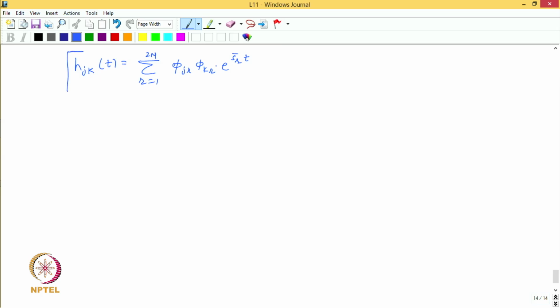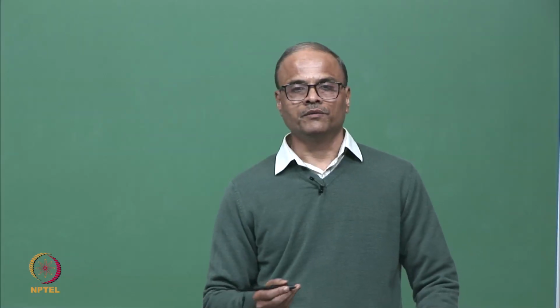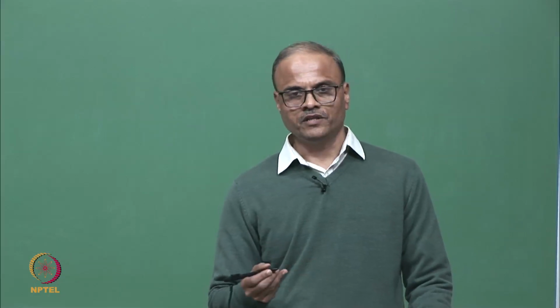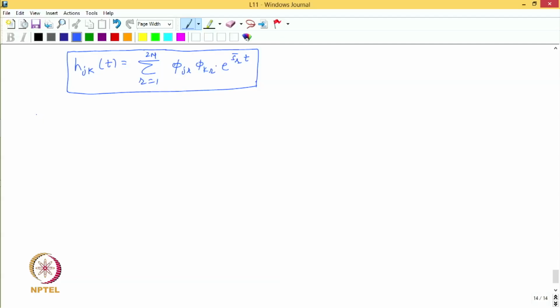So, to arrive at this, we have made use of the shifting property, and then after finding the displacement responses, which basically is nothing but the kth column of the impulse response function matrix, we just take the jth element in that vector, that basically gives us h j k t. So, now we can also define the response model in the time domain.